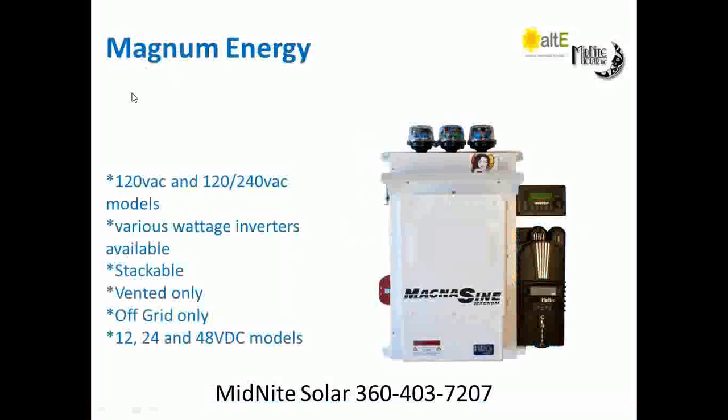They have various wattages available, all the way from, I believe, 600 or 800 watts up through to 4,400 watts. They have lower cost options with modified sine wave, and they have a full line of pure sine wave inverters. Everybody else's inverters are pure sine wave. Magnum is the only one you'll see here today that still offers a modified sine wave version as well. And again, remember I was talking about battery chargers. I've seen a lot of the modified sine wave Magnums installed just for battery chargers. They have undoubtedly one of the better battery chargers in the market. It's power factor corrected, very efficient and very robust.